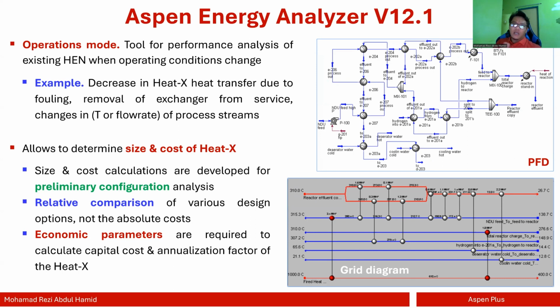Okay, the figure on the top right is just how it looks on the PFD, and how it looks on the heat exchange network is on the bottom right, where you have all of the nodes representing the heat exchangers. The ones with the red nodes are the heat exchangers utilizing the hot utility.